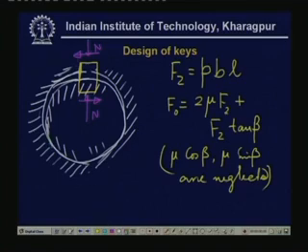So this is the contact region, and contact pressure develops. The exact distribution is difficult to say, but roughly it is expected that this kind of cosine distribution exists. Now, when you apply a torque over here and it rotates, the friction force develops.